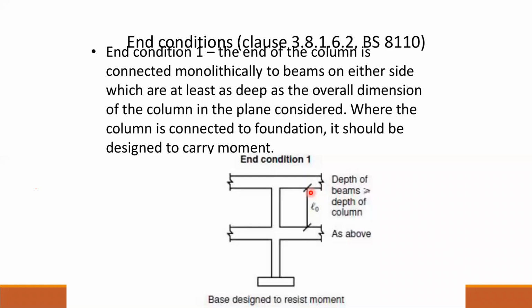Right? This is very simple actually. The approaches are quite easy, and the content is not difficult to understand. But when you practice this, you need to make sure that as an engineer, you are able to identify the selected criteria for these columns at the top end and the bottom end, and also the type of column, braced or unbraced.